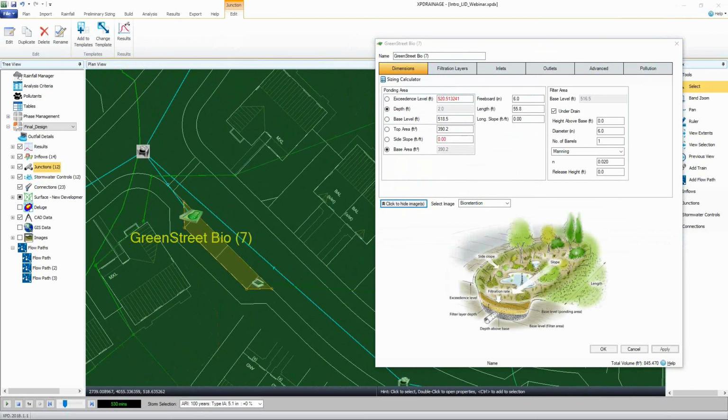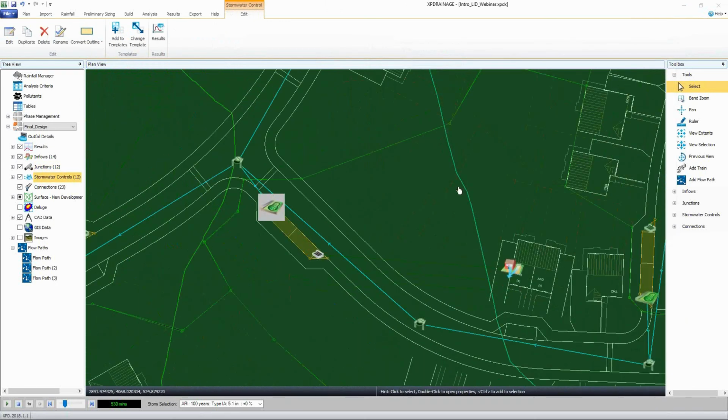So one more question here looks like about underground. What's the difference between underground storage and a dry well from a treatment perspective? So good question. Well, they might be semantics, they might not be. So a couple things. Typically when we start having a dry well, it's kind of a contained system. Sometimes maybe the bottom of the facility is open, so there can be infiltration.